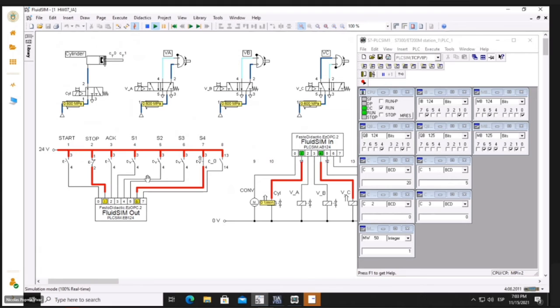This was achieved by using counters instead of timers, because in the counters you can stop the actual countdown that it's going through, so that way we can keep the count where it was. That's the implementation for the timers in this exercise.